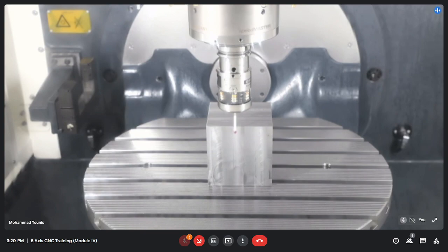Okay, I'll start the cycle now. The probe is at the right position. It just touched the front face of the workpiece, and the cycle is complete. Now I have also set the work offset for Y axis. Now I'm going to set it for Z axis. For that, we are going to touch the probe on the top surface of the workpiece. So here I'm going to select the Z axis.